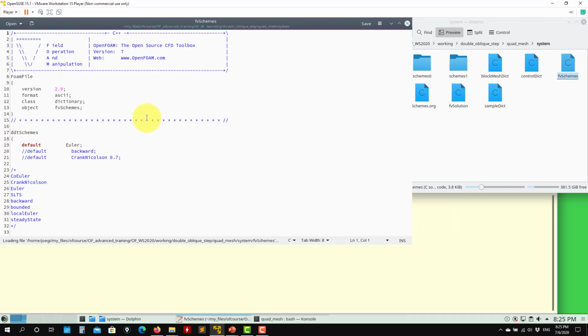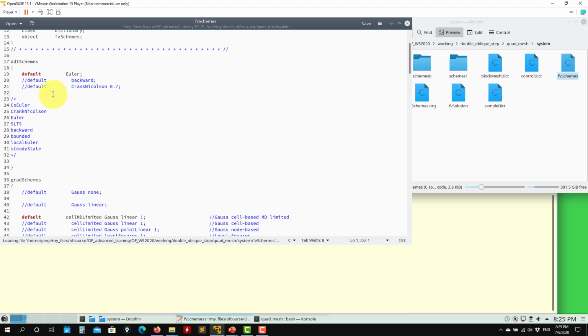Okay, so see that we go to the numeric. So this is pure convection, but it is unsteady. So we are using the Euler method. Later we're going to dedicate a little bit more time to numerical schemes in time, but Euler is first order accurate. We have seen that first order accurate is a little bit diffusive, even in time it can be diffusive, but as you get your CFL low, there's not much diffusion that you will add. In this case, the CFL is below 1, so it's okay, we have good accuracy.